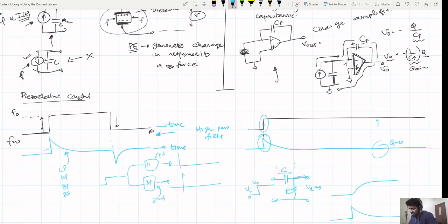The only thing I'll say is this. Here the frequency is low. Here you have infinite frequency. If this was in fact a band pass filter, the frequency response looks like this. The gain is 0 at infinite frequency, and the gain is 0 at 0 frequency. A band pass filter would not allow this or this. So you cannot have a large jump here because it is passing through this jump. The only filter that will pass through this jump is something that allows all high frequencies.